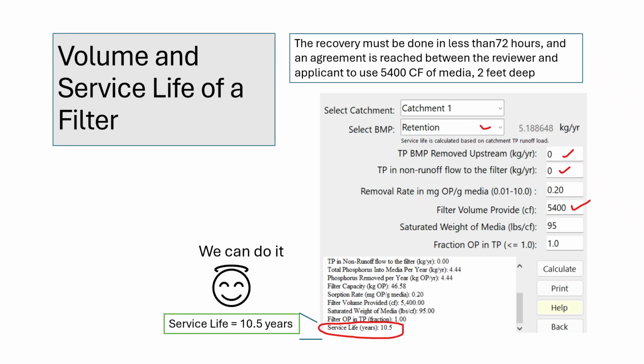The ultimate service life is then determined by this OP removal capacity, factoring in the media volume and the annual treatment rate for OP. For a deeper dive into these specifics, particularly concerning biosorption activated media, or BAM, please refer to our dedicated learning modules on the topic. The outcome here demonstrates that with careful planning and selection, a robust and long-lasting solution is entirely achievable.